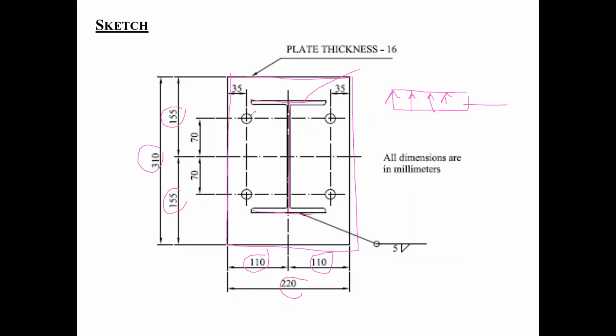And if you're going to have holes here to put your anchor rods or your anchor bolts, whatever holes you have here should be dimensioned with respect to the edge distance. We're going to talk about bolts pretty soon. 35 is a very common edge distance, okay?